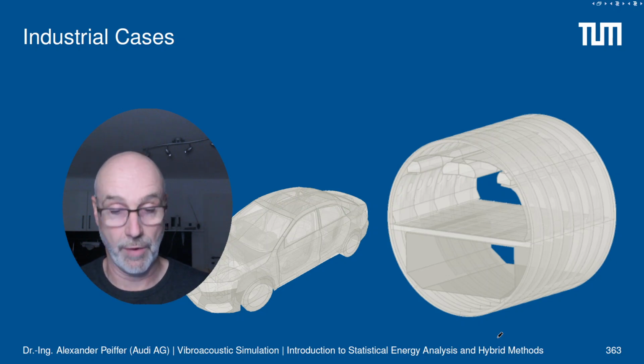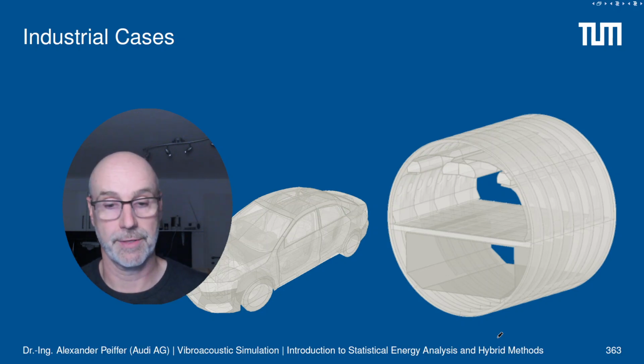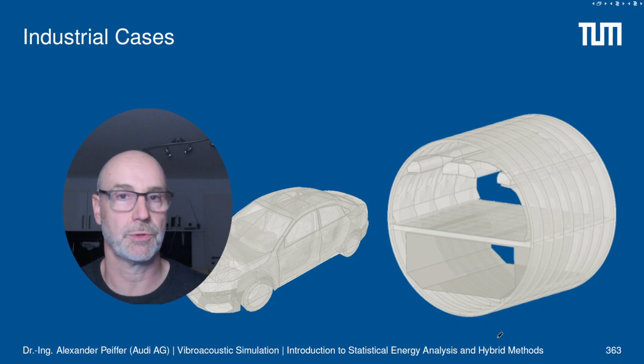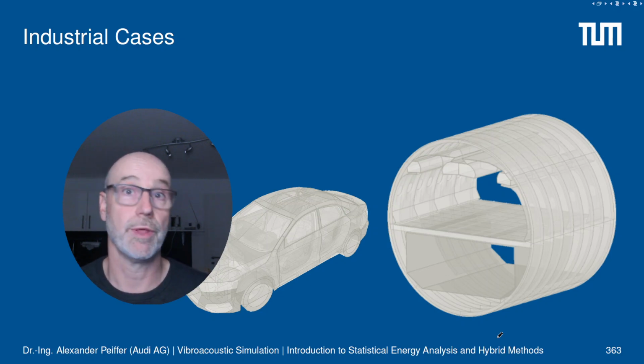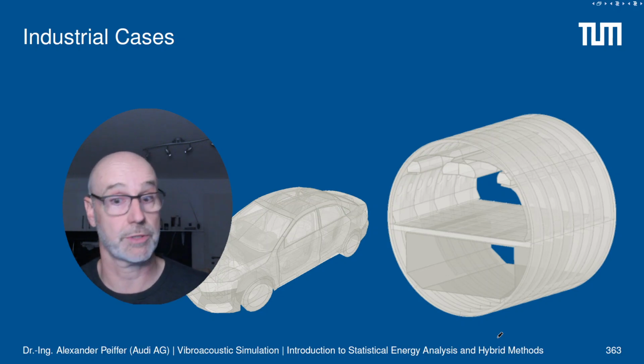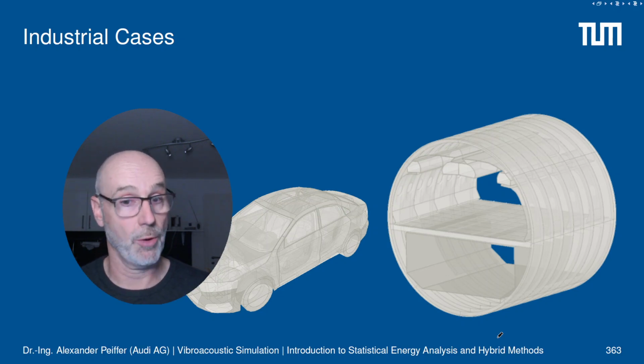Good. However, you have also seen you get a very precise and fast transmission loss result. And this is what is very often used in typical transmission loss calculations, because you don't have to recreate the diffuse sound field, because you have the diffuse sound field already implemented if you know the radiation stiffness with the given diffuse field reciprocity.